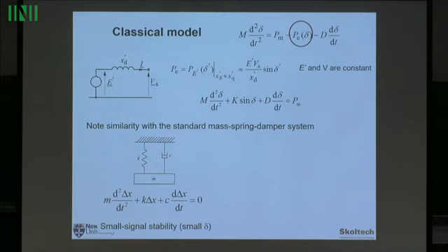That's why, as I said, those strings which link generators are springs. There will be some oscillations for small signal analysis, meaning when the changes of delta are small. So we can think about generators in the power system as connected by sets of springs. It gives a lot of results because there's a lot of theory regarding springs that is directly applicable. But remember, this is a linear model. It means we assume that delta is small.